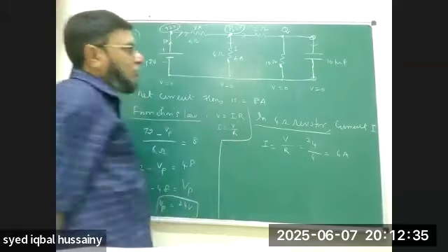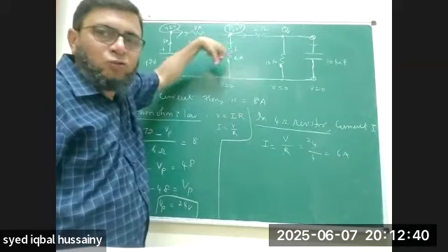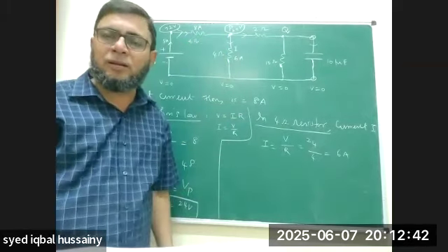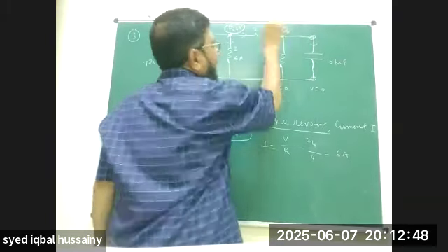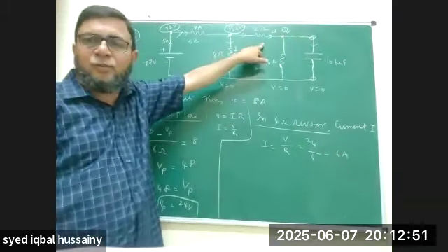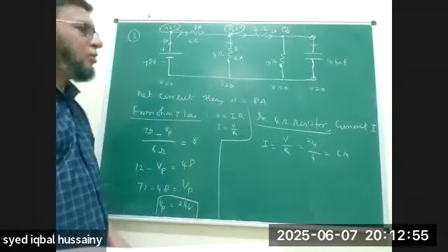6 ampere, very good. Write down here that 6 ampere current is flowing. Out of the 8 ampere, this track takes 6 ampere current, so how much remaining current will flow there? 2. Fantastic boys. So by the junction rule, 2 ampere current is flowing here. When 2 ampere current is flowing, then you can easily find out the potential difference there. Quickly tell me. I am getting something like 13.3.